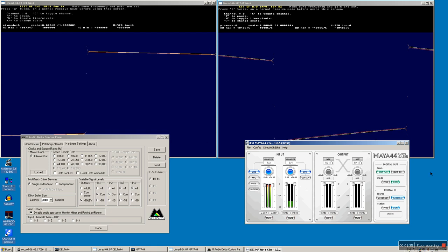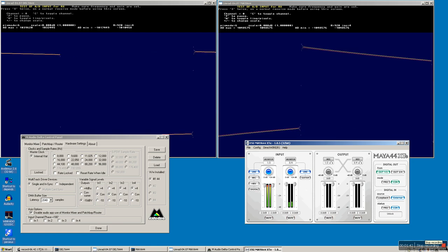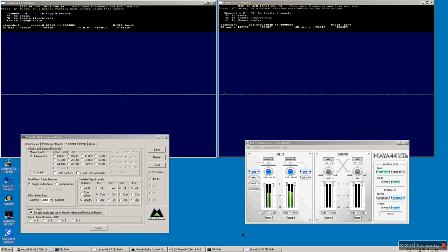So now I will disconnect the function generator and connect the IQ Plus. There is a pulse generator connected to the two inputs of the IQ Plus with a 3 dB coupler for the same signal to both inputs.